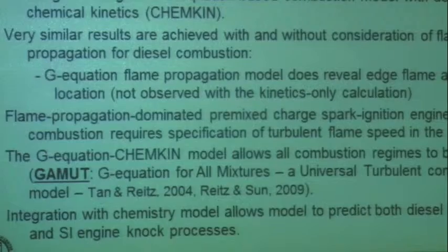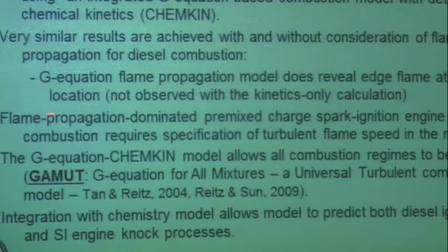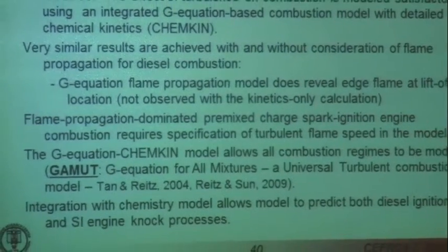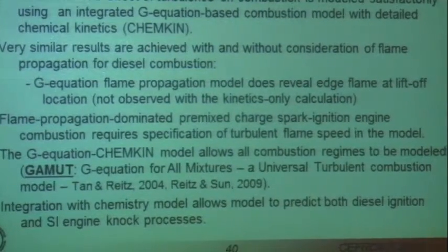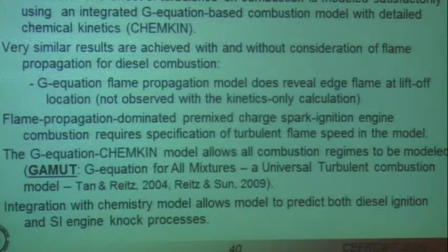And that's because the mixing is controlled by the injection and the turbulence generated. The G equation propagation model does reveal edge flames at the liftoff location of a lifted diesel flame. But that edge flame obviously would not be seen if you had kinetics only. All you would see is a sudden appearance of OH.